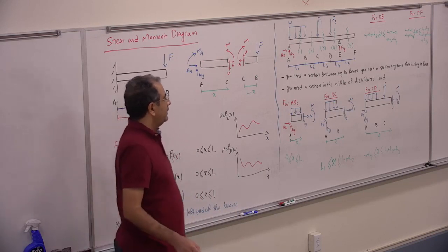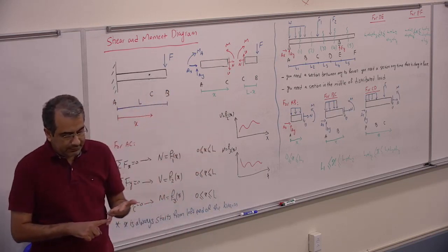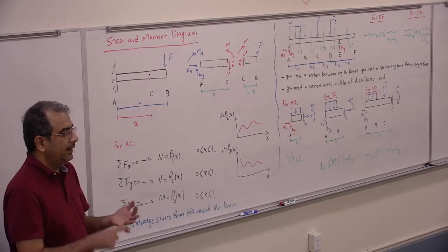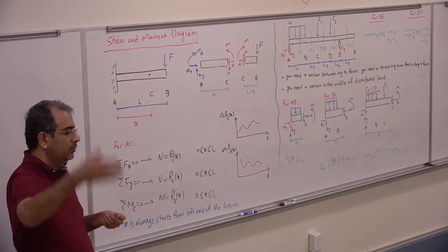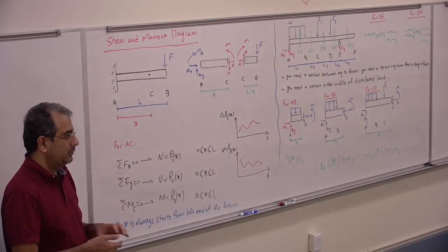So just remember that anytime we have a distributed load, we have to cut through it. Anytime there's a change in the external load, also we have to cut the section or cut through that section.